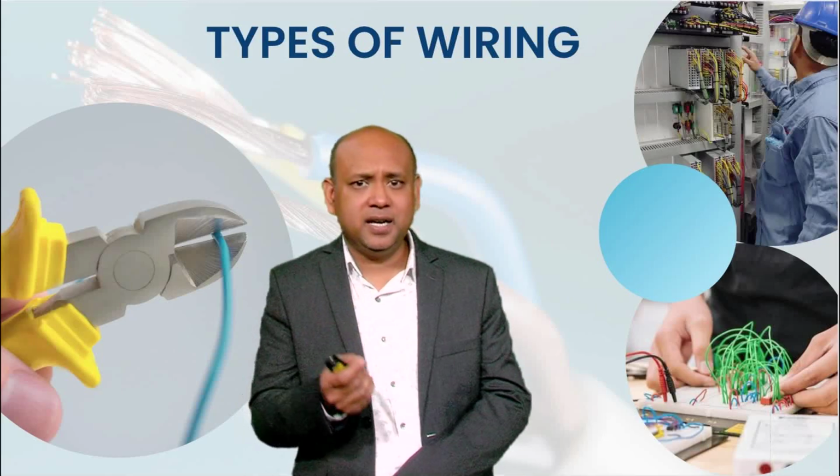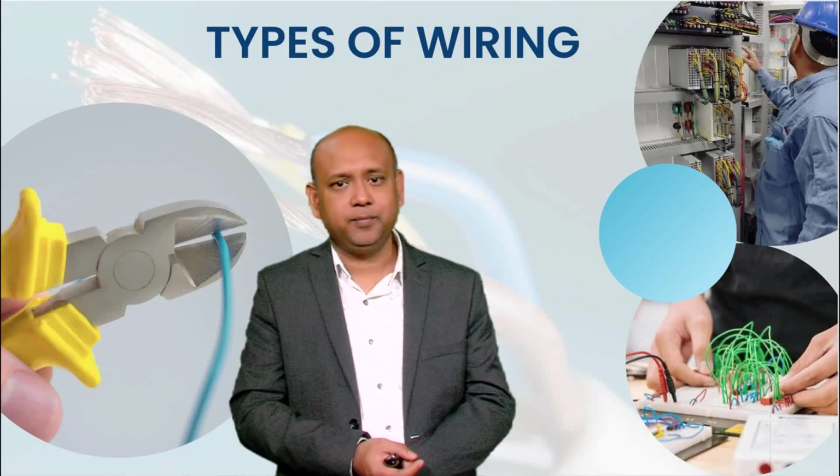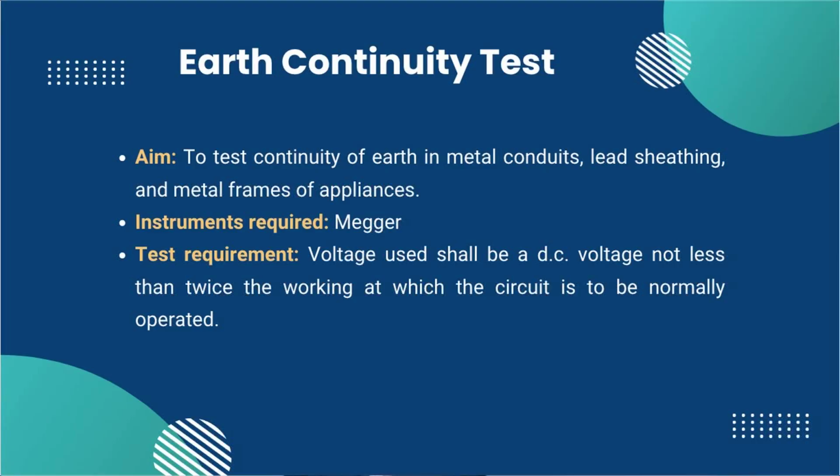Now, let us discuss the earth continuity test. The earth continuity test in an electrical installation is performed to verify that all metallic parts intended to be earthed have a low resistance path to the earth. This ensures a safe route for the fault currents, preventing any potential hazards. If there is a break in the earth connection, fault current may pass through a person, increasing the risk of electric shock. To conduct this test, a megger is required.